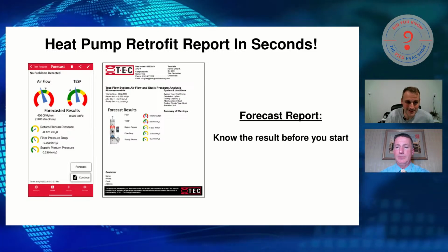Yeah. Dude, I'm guilty of that. I have done it. Hand raised, right? I have had to go in homes and replace supply ductwork because I missed the mark and my external static pressure was too high. Absolutely. I've been there, right? You move fast, you've got 10, 16 techs working underneath you. You're going as fast as you possibly can to line up installs, right?